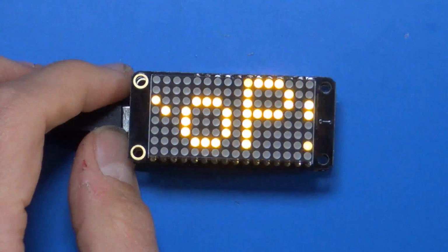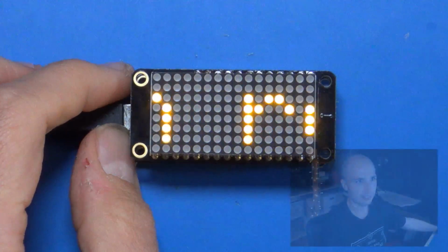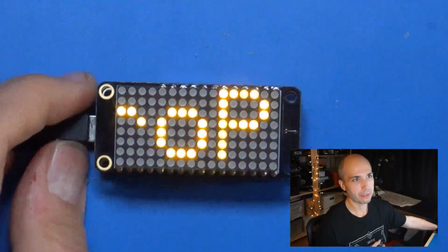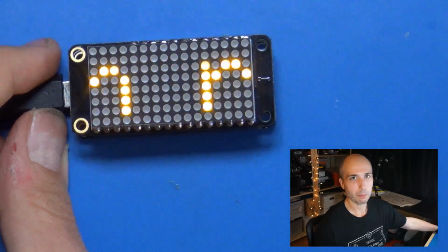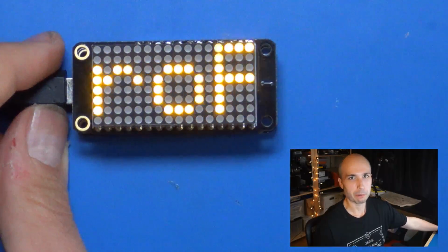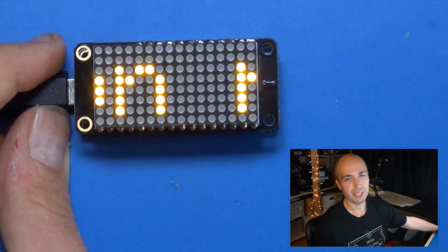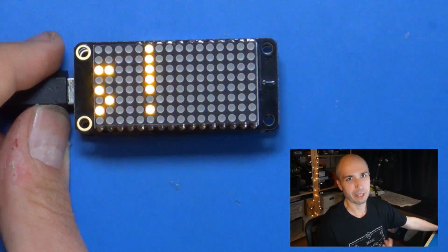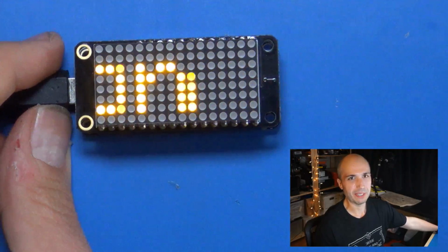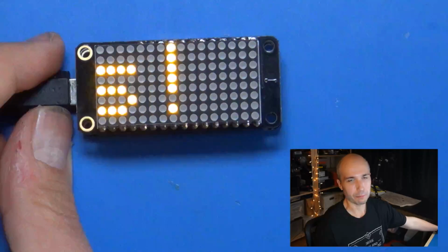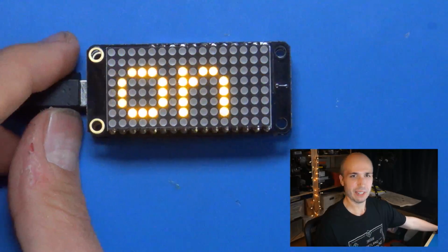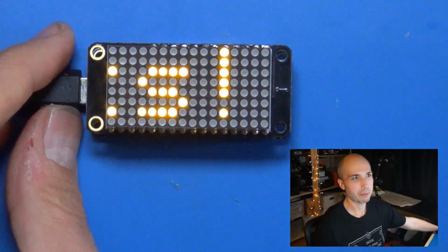And let me add maybe my head to the bottom of this shot so you can kind of see me right here. So I wanted to talk about how I built this demo and a really important challenge that I ran into that I think a lot of people are going to have as they deal with MicroPython, which is memory usage. Because when you use Python on a Raspberry Pi or your home computer, rarely do you have to worry about memory usage because you probably have a gigabyte or more of memory, and so even just fitting lots of data into memory is never really a concern. It's pretty rare that you deal with it.